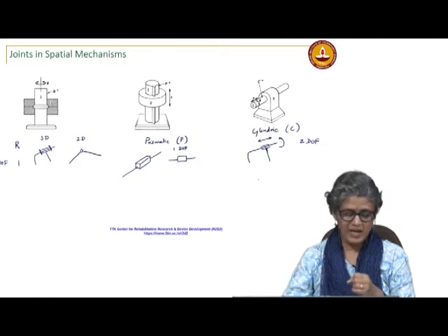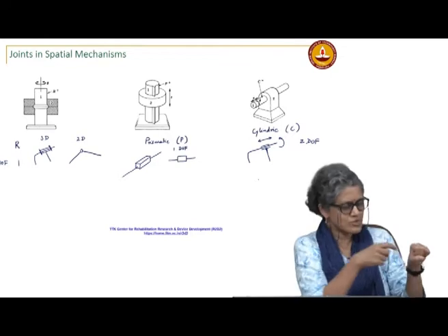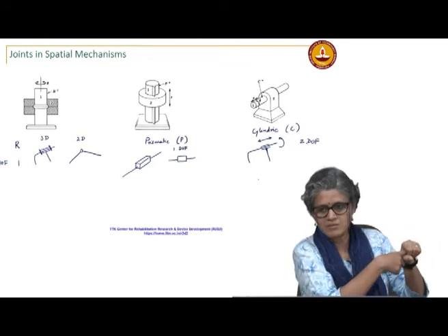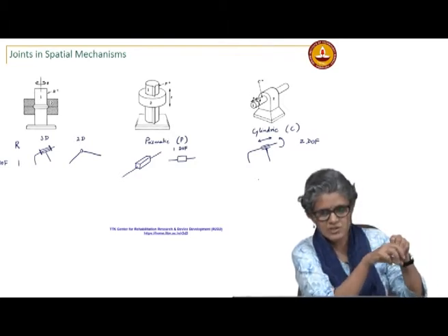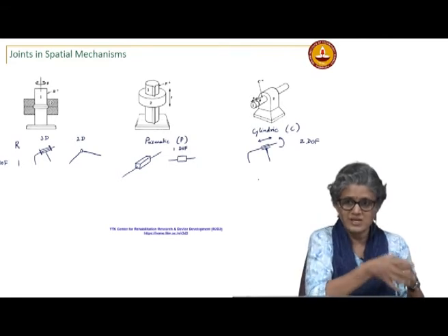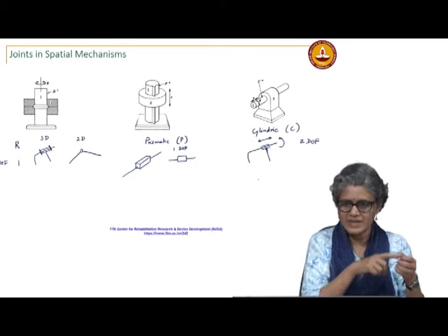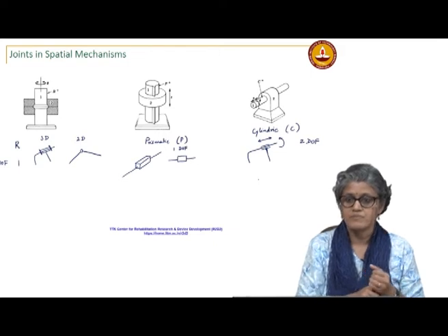No, if you have a pin joint, like this, if I connect two links with a pin that goes through like this, connecting these two links like your door hinge, you do not allow this motion. If it is a revolute joint, I will not allow this motion. One link cannot slide with respect to the other. But it moves along a slot.